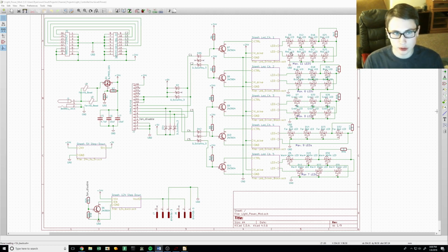How I distributed the 30 LEDs amongst the different colors was 6 green, blue, and white LEDs, 8 red LEDs, since their brightness is typically a little bit less than green, blue, and white LEDs, and 4 infrared LEDs, in part because they're very expensive, and in part because I don't need much infrared light for the plant light. These LEDs will result in a total intensity of at least 1,442 lumens, plus the infrared.